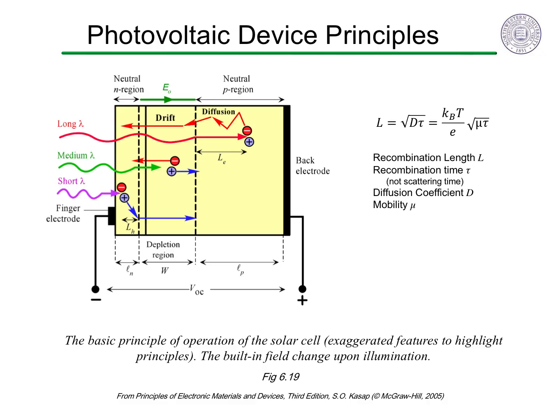Thus, the active region of the photovoltaic is not just the depletion region, but also anything within a recombination length of the junction. Because recombination length is related to diffusion coefficient and recombination time, which is also the mobility and recombination time, the mu-tau product is often considered an important materials metric for minority carrier devices such as photovoltaics.